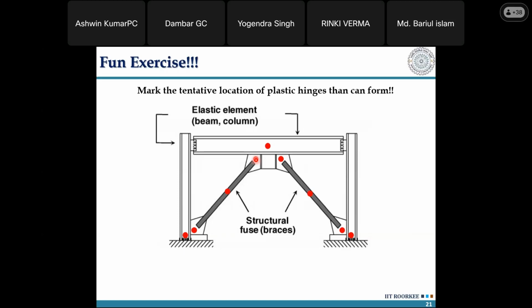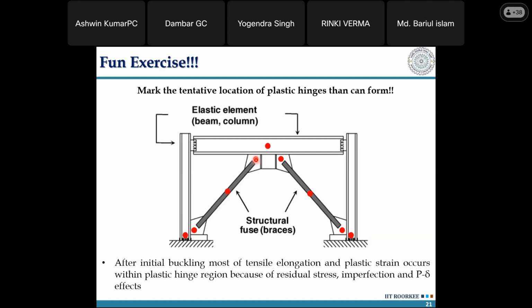I mean rigid connection है. With respect to the detailing, you can give a rigid connection, but you have to think about the anchor forces. The main problem is the connection between the steel brace and the RCC element. There are many options available right now: if you're casting fresh concrete, things can be embedded inside, which will give better performance. But even for retrofitting of an old RCC building, post-installed chemical anchors are already available from different companies, which can also be used. So yes, it can be used there, right?